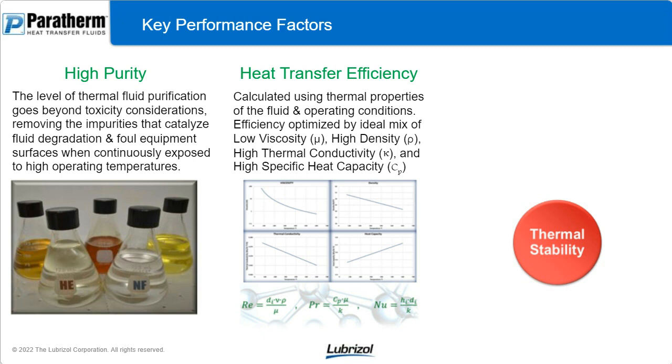Degrading the fluid will cause problems in the equipment, damage the equipment, foul surfaces, plug lines, and block heated surfaces from doing what they're intended to do. Create sludge, jam up your expansion tank little switches. So efficiency is mostly about how well that fluid's holding up over time, how well it's going to be protecting the investment of your equipment, ultimately your investment in your maintenance, and the safety of your people.